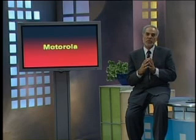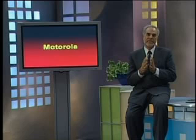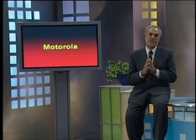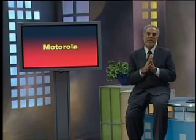Similar to what we had in SPARC, in this case the condition code register or status register is also available. It's a 16-bit register, and we could say that there are 2 bytes. The lower byte is the user defined and the other one is the system defined byte. We'll look into a little more detail, and let us see in the next slide the programming model of this Motorola 68000 family.